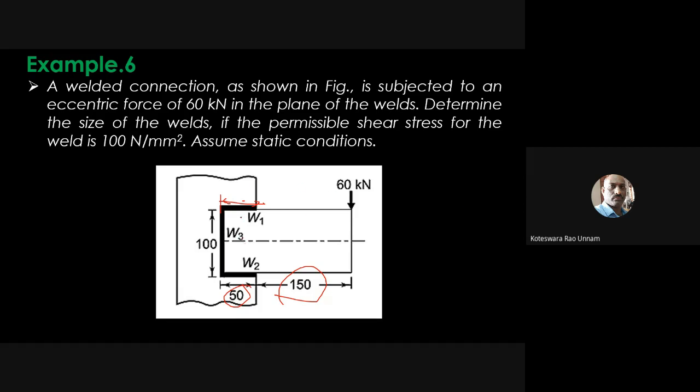Then we need to identify the center of gravity of this weld so that you can transfer this load from this location to this center of gravity. To find that center of gravity, again you have to use your data book.